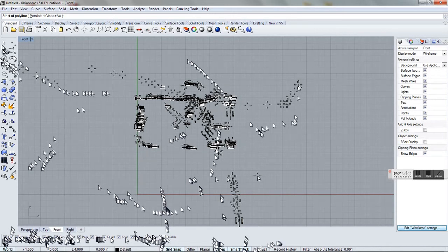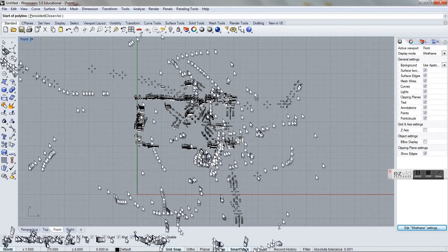When you're starting your drawings, my suggestion is to start at the origin right here, which is 0, 0, 0. Since we're exporting this into another program, very often other programs will need to know where the origin of your part is, so it knows where it's located in space and where it's measuring from, essentially.